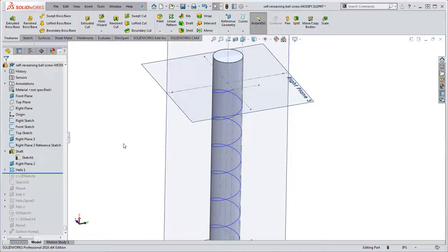So what we want to do is we want to be able to create some sketch geometry. We don't want to necessarily rely on helix because we can't really do much with that helix. It's kind of static. It's in its own little world over here. But we can borrow that geometry in order to create like a 3D sketch spiral. It's going to be sketch geometry rather than a helix over here, and we can make modifications to that where we can't to the helix.